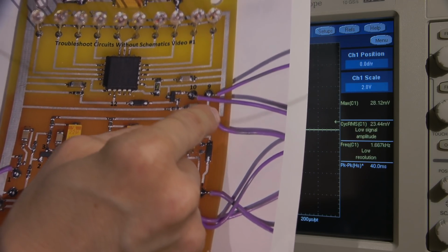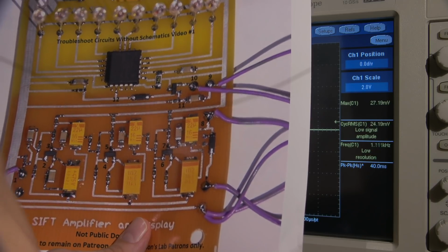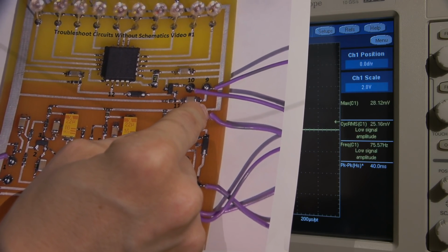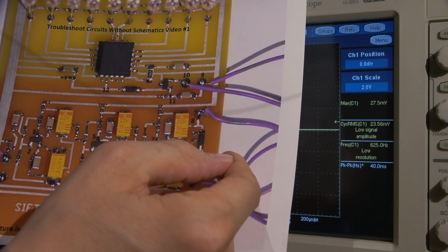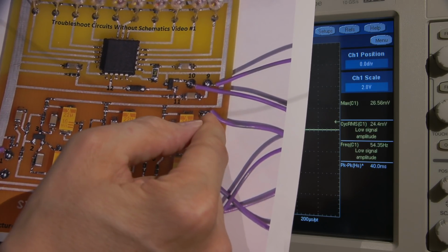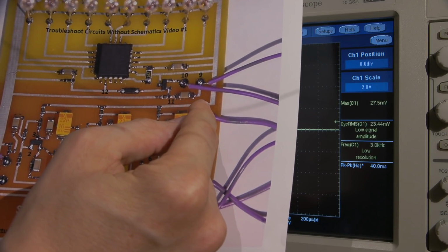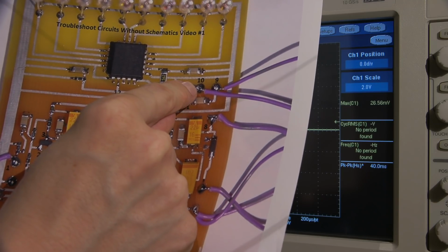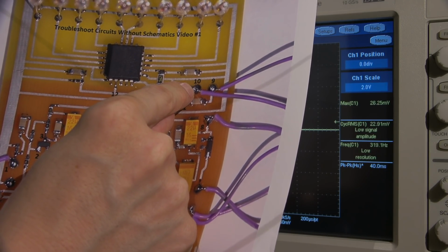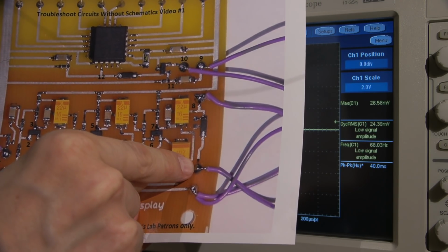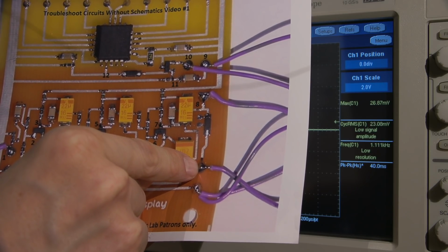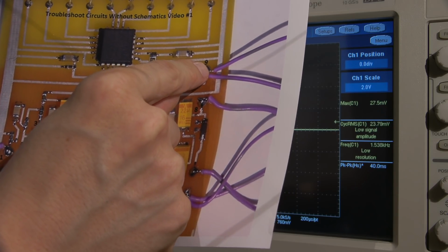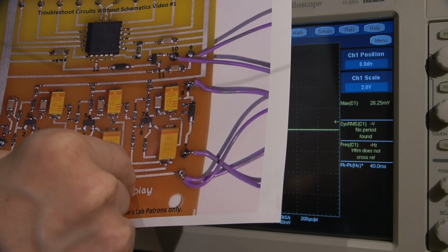So with this in the gain position, because this thing here would be in some form of a device and it would obviously be labeled at this point, right? So we'd flip it over and we'd find that this is in the gain position that would be marked gain. If we follow the wires, we would find that the gain position comes out here at number 10. Now, in the gain position, this is open. If we click this to the intensify position, it routes the signal to number 9 here, and it closes this diode.